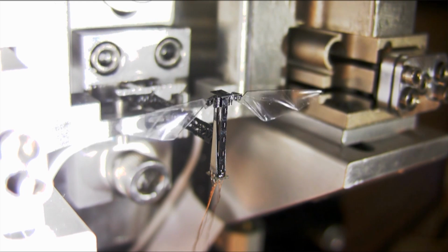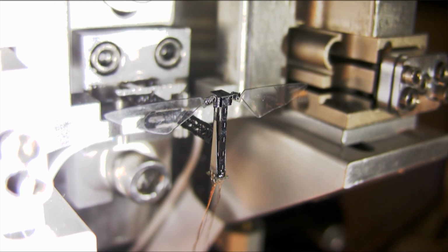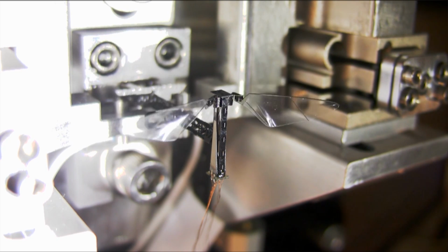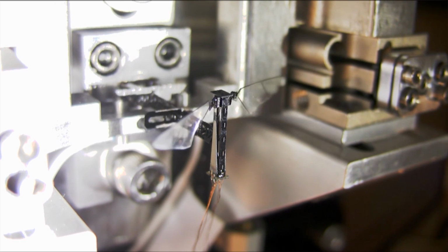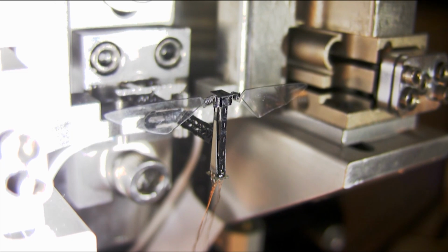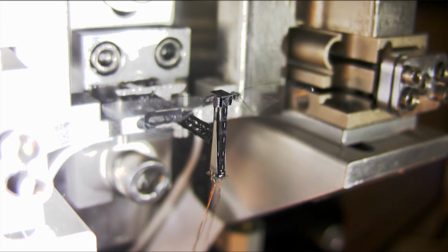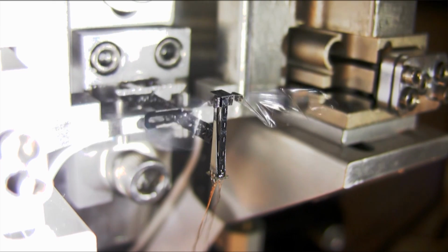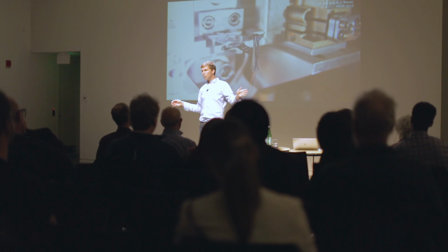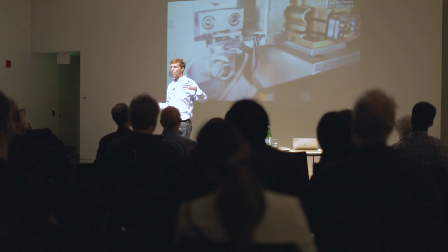And so the way that this works is I flap these things, and it's basically like an amplitude modulation scheme, with a cross product with the way a helicopter flies. I flap these things at resonance, so I don't change the frequency of operation. I just create bilaterally asymmetric amplitude changes. If I have a fixed frequency and change the amplitude, I'm changing the velocity of the wing. The lift force generated goes as velocity squared, roughly.